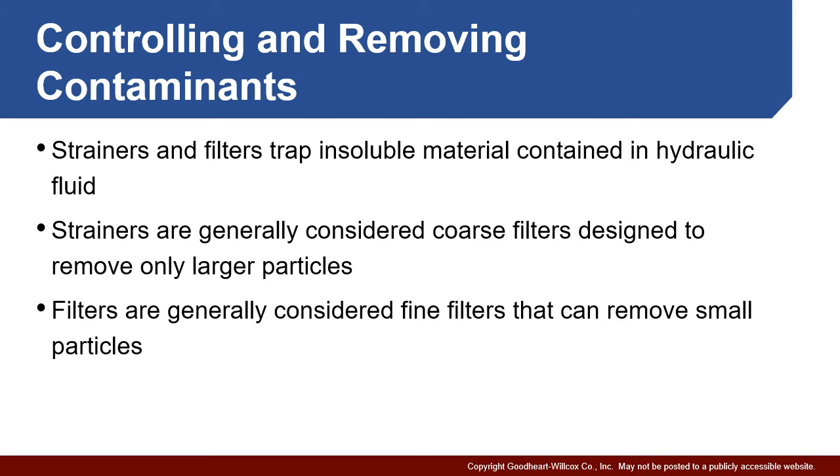Filters, on the other hand, come in a number of different forms, but they're usually designed to do fine filtration. So they're trying to stop small particles from getting through. You could come up with some sort of very fine mesh for this, but keep in mind that potentially is problematic because that's going to cause a lot of pressure drop. So you're always going to have to balance the amount of filtration versus the cost in terms of pressure and efficiency of your system, because there is a cost associated with this. You're going to have to force the fluid through a strainer or a filter.